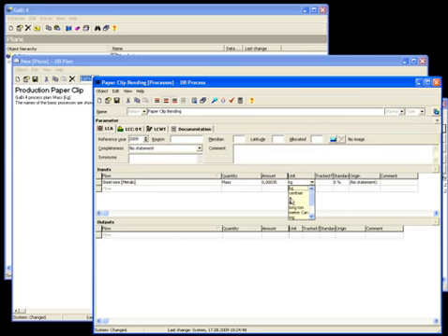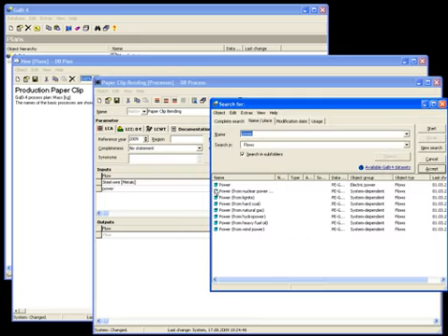Material and energy amounts can then be added and units specified. Units can be chosen from a drop-down list and can be changed at any time. The quantity will automatically update for the new units. By entering power as an input, a variety of possible flow matches from the GaBi database are listed.